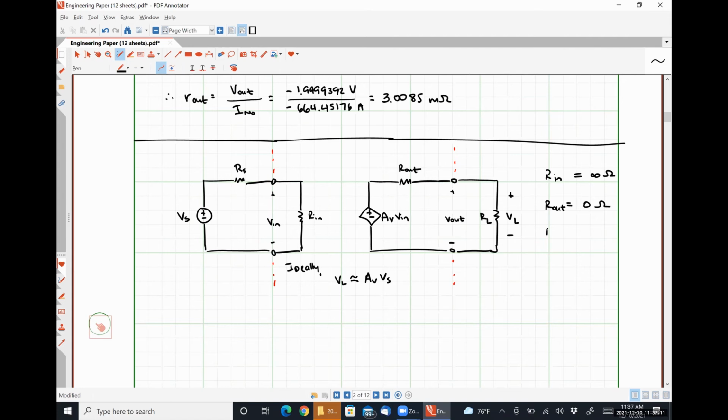We would want our open loop gain, AVOL, to be infinitely large, or as high as we can possibly get. Because the higher that we make that open loop gain, the more well-behaved it will be as a closed loop gain by the application of feedback. Okay.